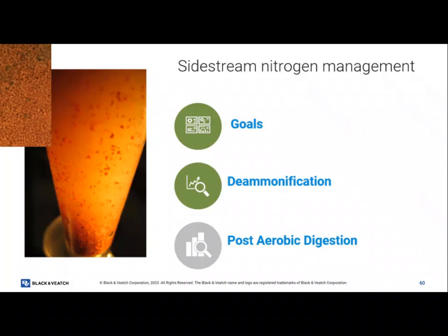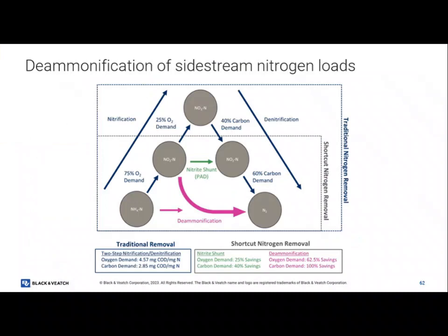How many of you have seen MBBRs, where it's this plastic media that floats in the aeration basins? We've got one here. They grow on that media, and you can't lose the media then. And your SRT can be infinite with the media. So you're either growing this granule form, or we're growing on a media to essentially get that deammonification. And that's how we're getting past that.